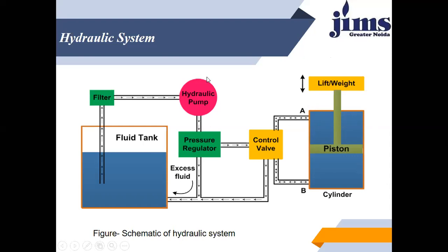So let me discuss the components of the hydraulic system. I think the figure is before your eyes, on your screen. You must see the pump. What is the function of the pump? It delivers the high pressurized fluid to the pressure regulator, okay? Then the pressure regulator: what is its work? It limits the pressure in the system. Then we are talking about the valves, so these control the flow rate and the pressures, right?